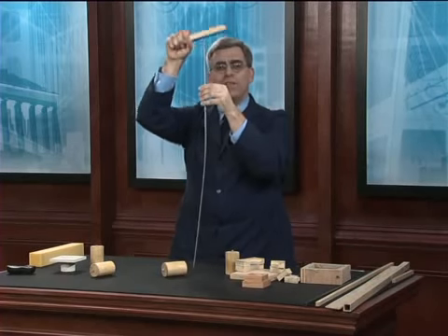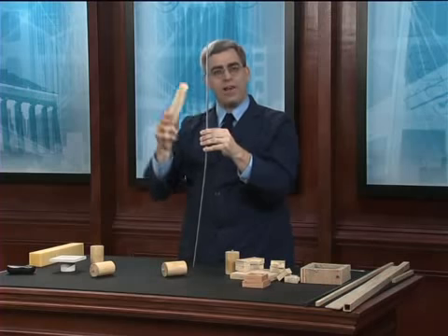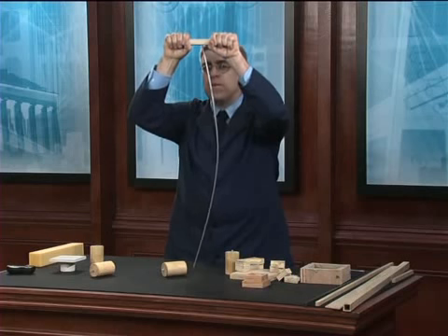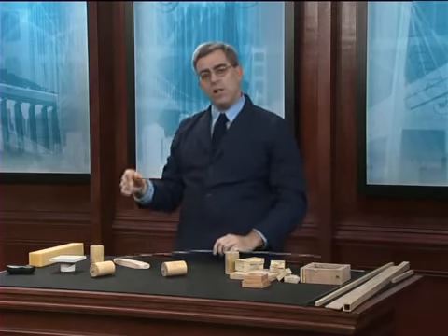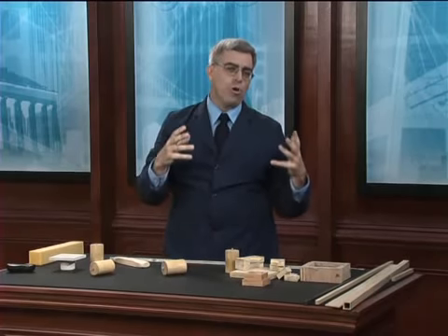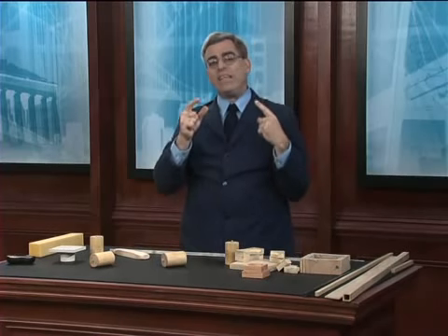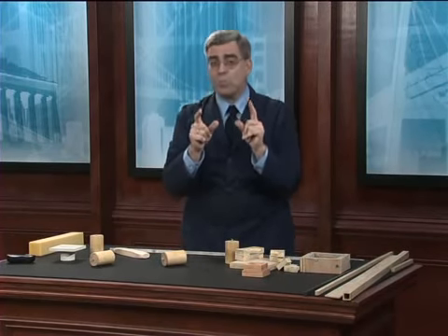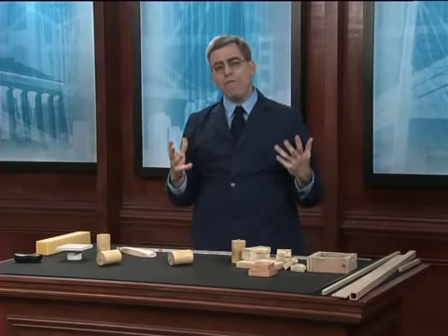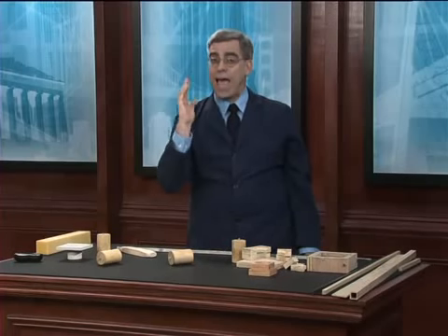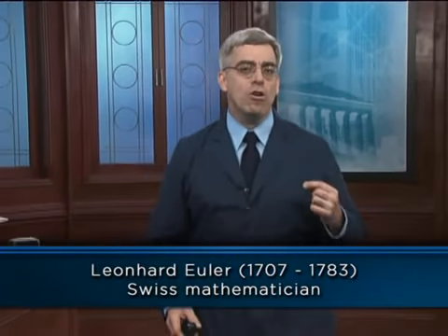It's important to recognize that even though a buckling column deflects laterally, the load that I am applying is purely axial, like this. The lateral deflection doesn't occur because the column is initially crooked or because the axial load is slightly off center. Yes, these conditions would certainly cause the column to buckle at a slightly lower load, but they don't cause buckling. If we could somehow build a perfectly straight column and apply a perfect axial load, buckling would still happen. We owe our understanding of buckling to the genius of one man, the great Swiss mathematician Leonhard Euler.